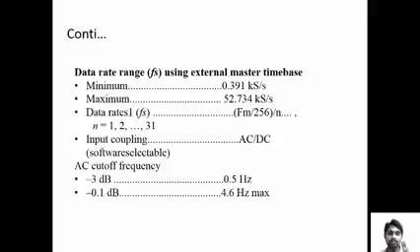Input coupling, AC or DC, is software selectable. I already told you about IEPE. The AC cutoff frequency is -3 dB at 0.5 Hz, and -0.1 dB at 4.6 Hz maximum.